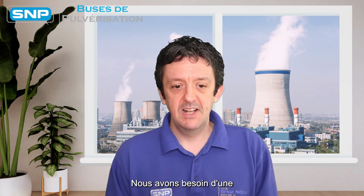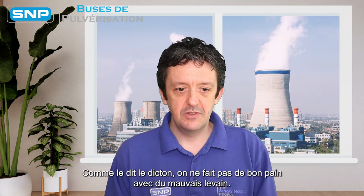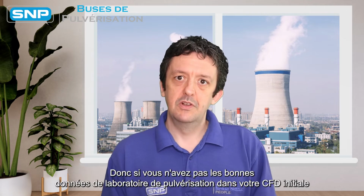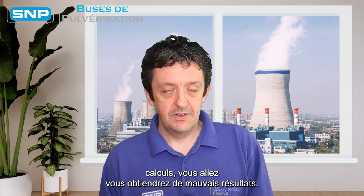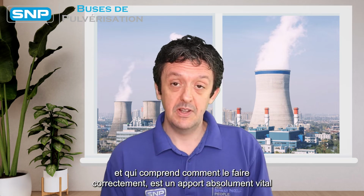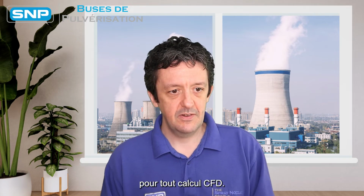We need a proper spray lab that understands the subtleties of drop size measurement techniques, and this is an absolute must. As the saying goes, if you put garbage in, you get garbage out. So if you don't have good spray lab data going into your initial CFD calculations, you're going to get poor results out of it. Having a proper spray lab that can measure those drop sizes and understands how to do that properly is absolutely vital input for any CFD calculations.